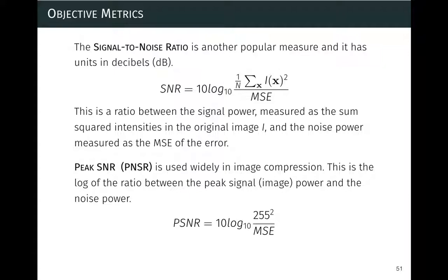Another classic one, and possibly even more classic, is the SNR and PSNR. So what you measure here is the ratio of the squared signal divided by the mean squared error. And that kind of comes back a bit to Weber's law and so on. You're trying to take a ratio between the difference, so that would be your MSE, and the magnitude of your signal here. So that's the signal to noise ratio, and that's in log space, right?